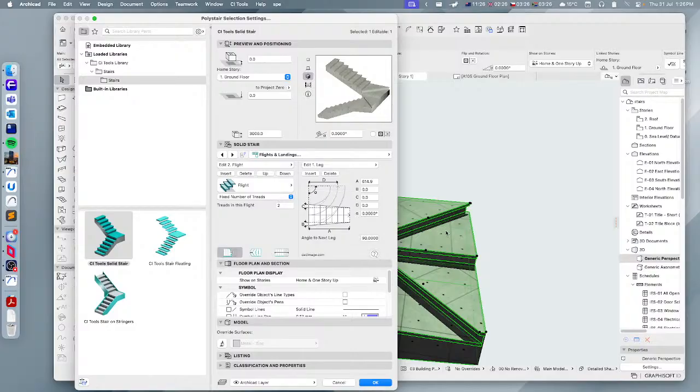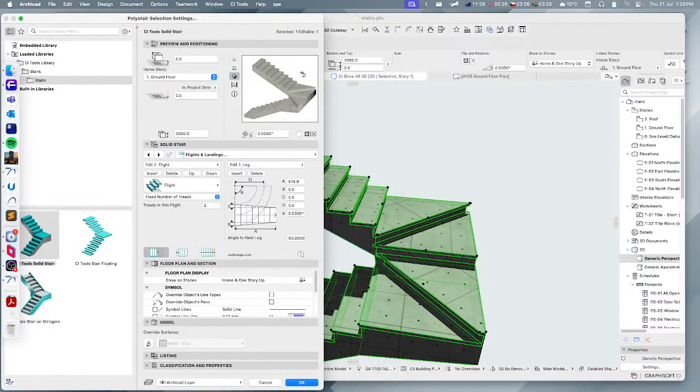You've got it sorted. You could try and do it using just 1 turn that did the full 180, but I find that gets a little tricky because you don't always want it to be coming back exactly onto itself. Sometimes you want to have a gap in between and that sort of thing. It's much easier to draw while you're drawing the line work and floor plan. You don't want the nodes sitting all on top of each other because it gets quite fiddly there.